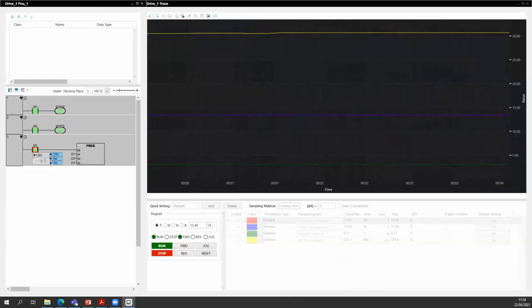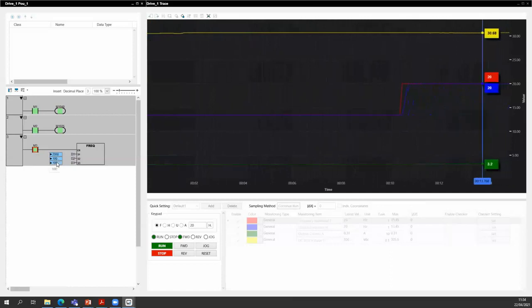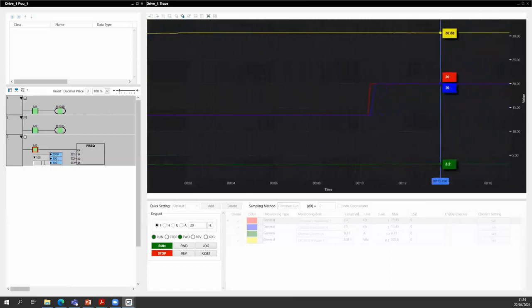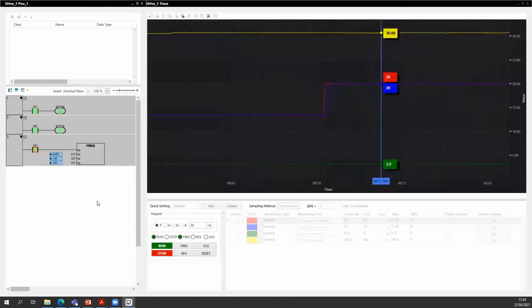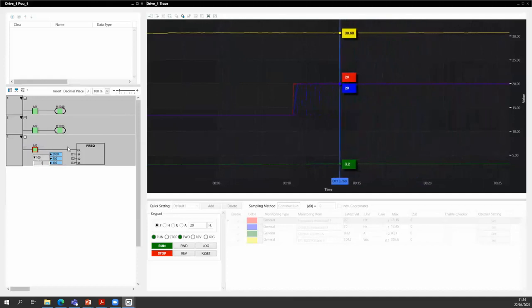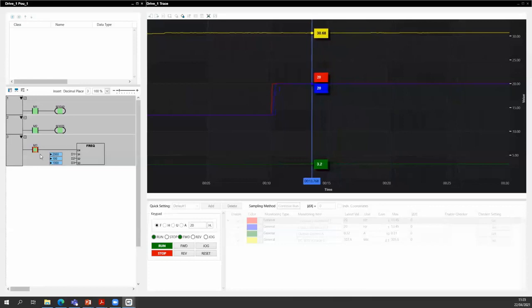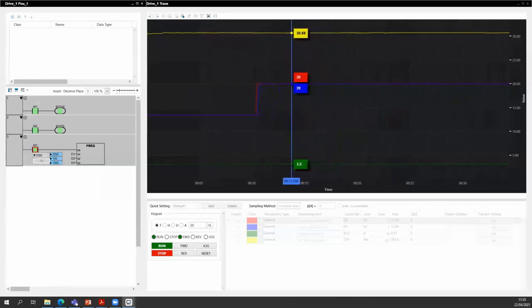I can change this to 20 Hertz. So I set here 2000. And then you can see it here. I can change the deceleration ramp to be much slower. So I can set it to 10. And yeah, so now it's okay. I can give it a frequency command of 10 Hertz.